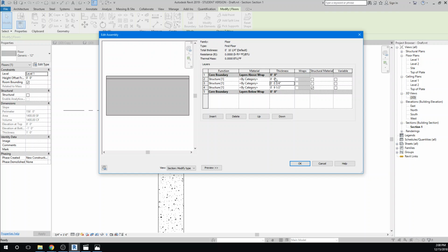That, and then some other surface. So let's just try to make it even numbers. So I'll just make this a 1/4 inch. That would be like the top flooring material. I'm thinking maybe we'll just leave this off. No, that'll give us, I'm sorry to be thinking out loud, that'll give us 10.5 inches, and then with our stud to support it, that will give us our full 12-inch buildup.